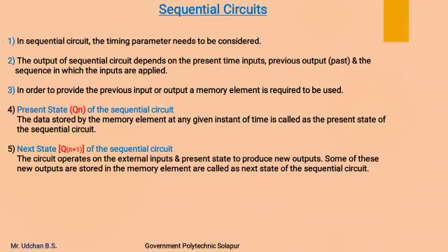So we will start with the sequential circuits. In sequential circuit, the timing parameters need to be considered. The output of sequential circuit depends on the present input, previous output, and the sequence in which the inputs are applied. In order to provide previous input or output, a memory element is required in this sequential circuit.